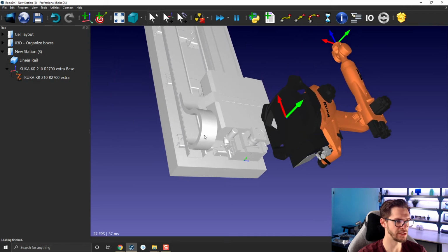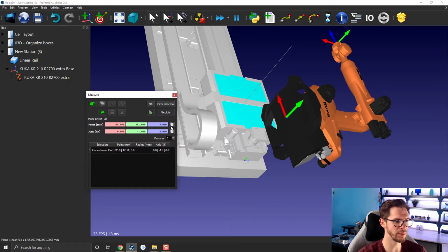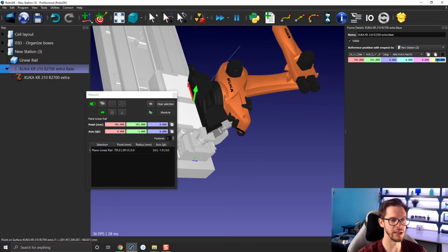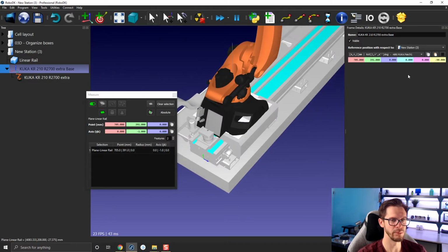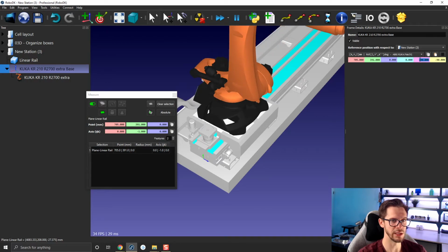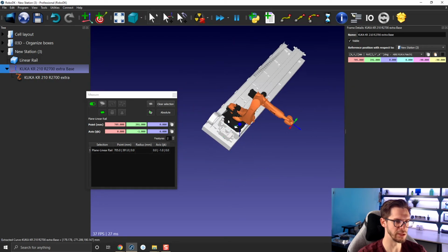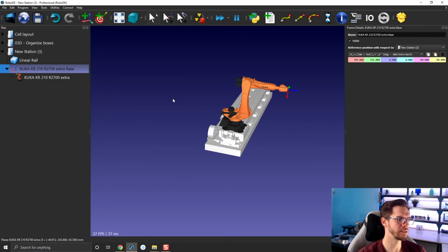So in this case here, I can simply go Tool, Measure, Snap, Detect Plane, come here, it will give me the middle plane. Click OK, click Copy, double click here, Paste, and then I just need to rotate that up a bit like that, and potentially rotate like this too, if I don't want to be obstructing this piece here. So that's a method. I'm going to show you one last thing with regard to that.